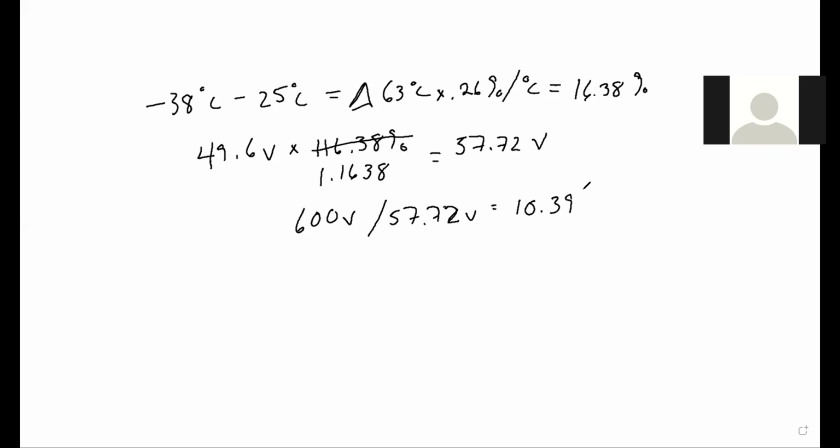Okie doke. Hey, Ursula, I'm working on your problem. We've already determined the size of the array. You can review that in the video, but I'm working from an 18.3 kW array. We've determined that we can put 10.39 maximum per string. Now, I was hoping we could get 11, because we determined 22 panels in each array, and we're going to do 2 arrays. So that would have been quite easy.